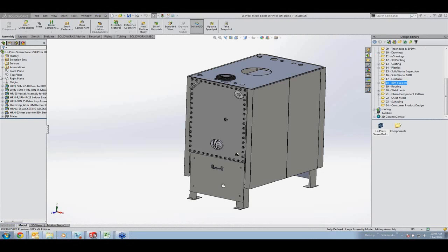Creating planes in SolidWorks is now easier than ever. When you create a reference plane and select a point or a vertex between 2 faces, you now have this option to create a plane parallel to the screen, the actual orientation of the screen. I can now use that plane to create a section view. I can rotate this around and it maintains that section view.